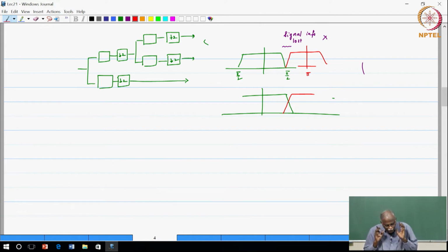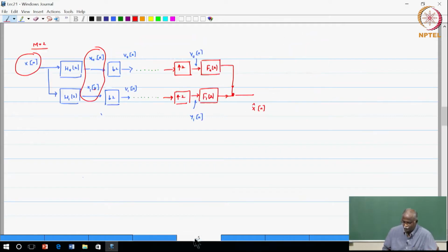So we go into this subband analysis with the following aspects in mind. I want to downsample by the maximum downsampling rate possible, which is M. Given practical filters, each of these must have approximately bandwidth 2 pi over M, which means that there will be overlap between adjacent subband signals, which is fine, and which may result in aliasing, but that is where the challenge lies, and that is what we are going to be looking at in today's class. So that is a quick review of where we are.